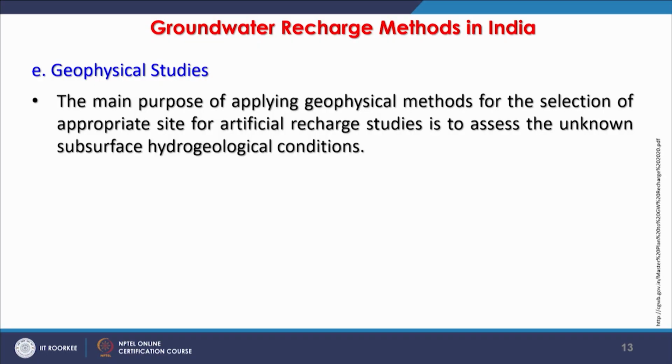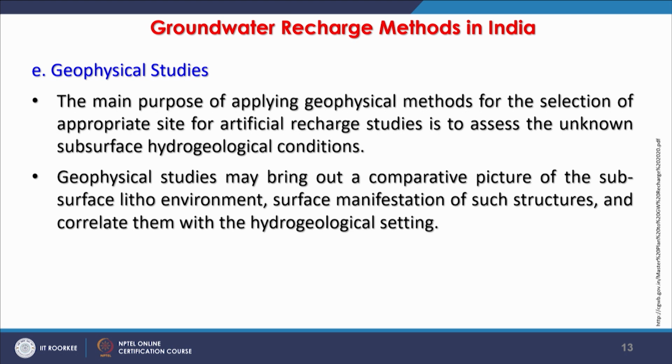So, would it be possible to monitor the performance of such things, for which we also require maybe geophysical studies. The main purpose of analyzing these methods is the selection of an appropriate site for artificial recharge studies, and that will assess the unknown subsurface hydrogeological conditions. So, all these studies are required in case of large groundwater recharge structures.